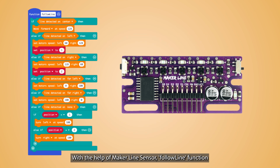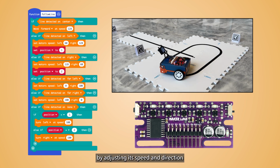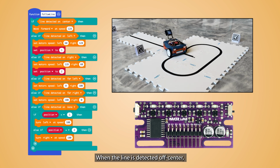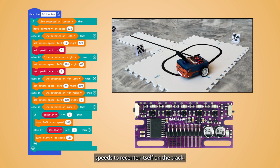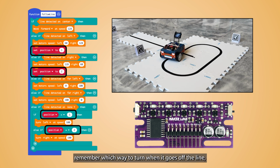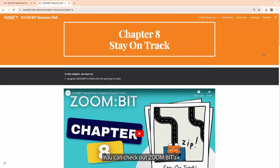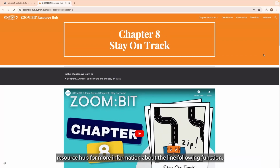With the help of Maker Line sensor, the follow line function allows ZoomBit to follow the track by adjusting its speed and direction based on the detected position of the line. When the line is detected off-center, ZoomBit adjusts its motor speeds to recenter itself on the track. The position variable helps ZoomBit remember which way to turn when it goes off the line, so it can get back on the track when it sees the line again. You can check out ZoomBit's resource hub for more information about the line following function.